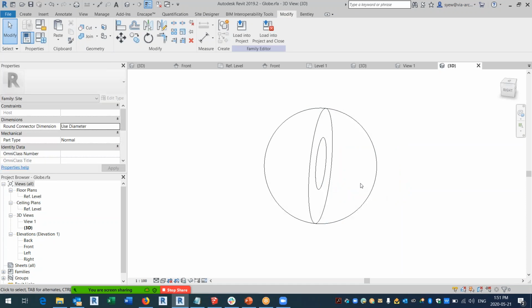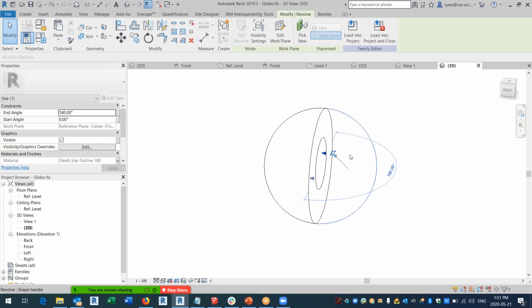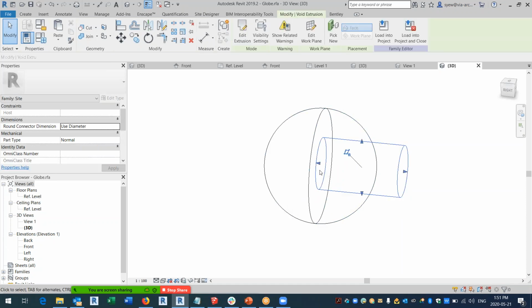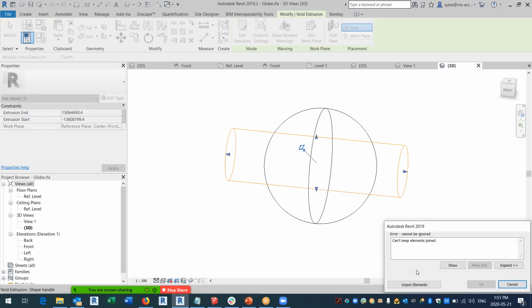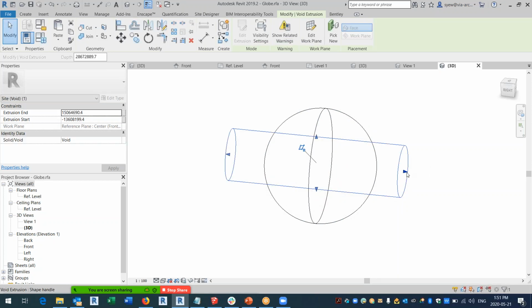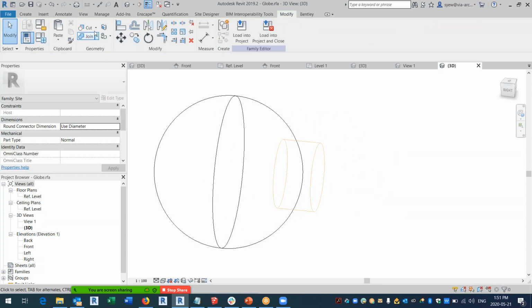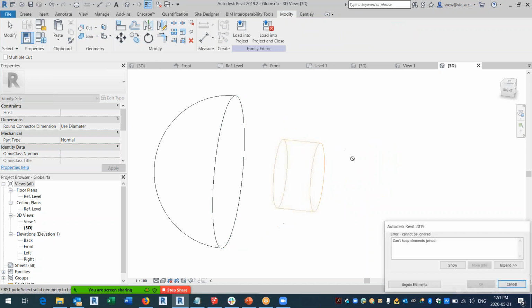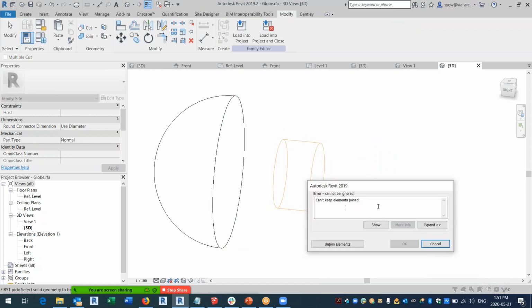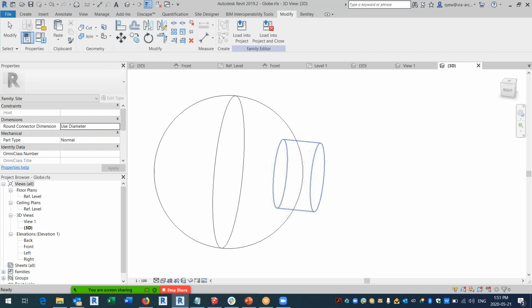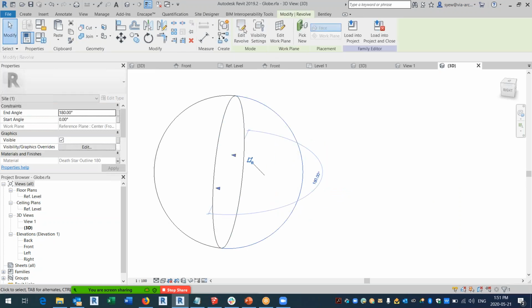You notice that right now, if I want to cut this particular object with that, it just will not cut. Revit just unjoins stuff. So if I want to cut this with that, you notice that Revit just will not work. So the larger the objects, your void becomes useless. There's no way you can do it except you kind of have to do this.